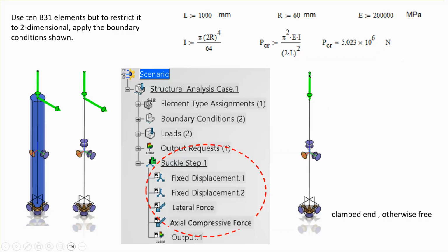In other words, there is no eccentricity of the load. The load is in the direction of the line. There is no imperfection in the geometry. The geometry, for example, is always a circle of the same radius. But this assumption is impossible for manufacturing purposes. Or there may be a lateral force acting because maybe there's a wind load here. This is a particular column in a structure. There's weight on top of it, and then there's a lateral force.